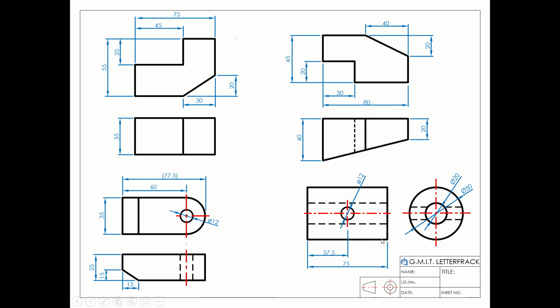You can see I've given my diameter for the outer one here, not the radius, but the diameter, because if I wanted to check that, I would measure it with my vernier calipers and it'll be the diameter that I'll be checking. Same thing applies, my diameter 20 for the hole, because it's the diameter 20 drill bit. Same thing, diameter 12 here, like that.